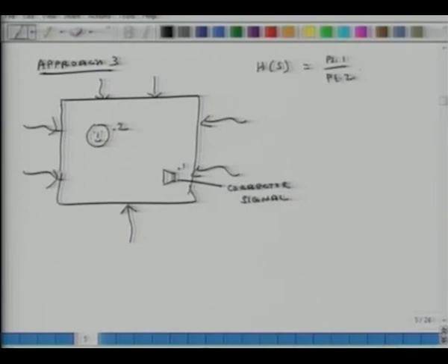What that physically means is that if I generate a particular sound profile at point 1, what will be its frequency spectrum at point 2, right. That is what the transfer function is all about. So based on that understanding, once I have this Hs, which is a fairly easy thing to do, you generate a broadband noise source here, you measure it here, and then you take the ratios at every frequency, you have your phase and magnitude plots for this transfer function.